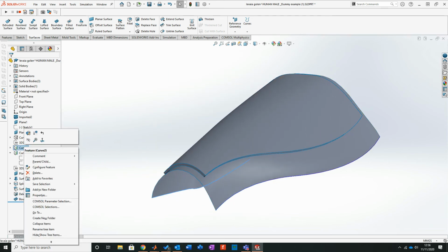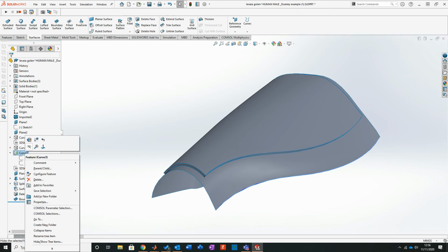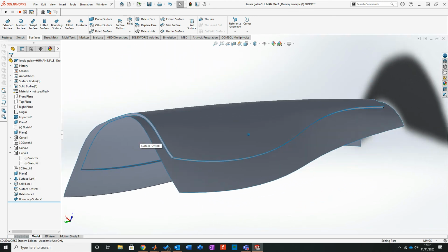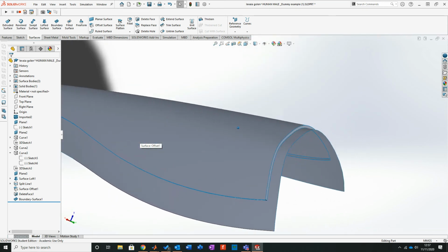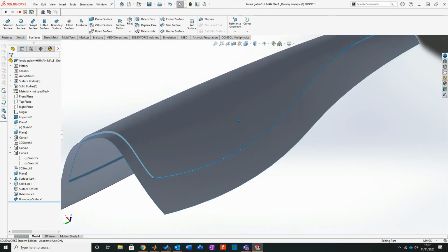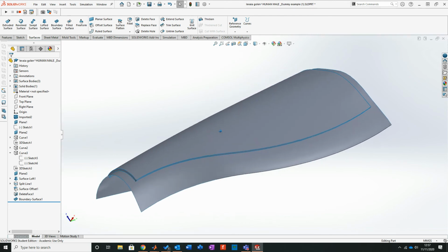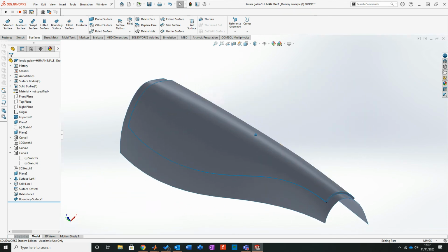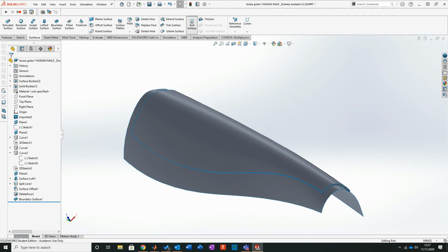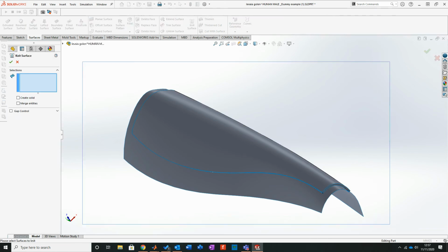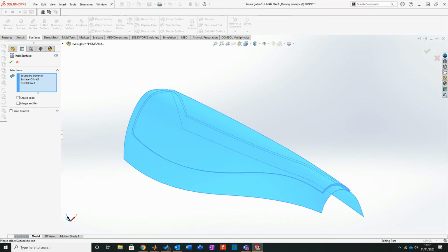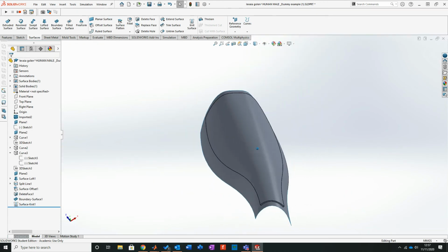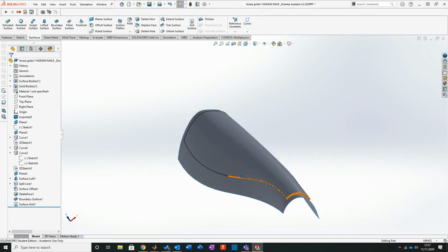I've got a curve turned on there, which I don't like, so hide and hide. Now, as ever, you're going to have to take a nice little journey around the actual part, make sure that there's nothing illegal on it, make sure everything's right. From what I can see, it is right. What I'd like to do now is knit all this together, and then merge the entities to create that profile. And what that does is it creates me an exterior part.